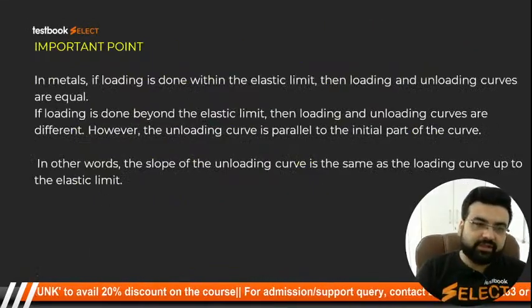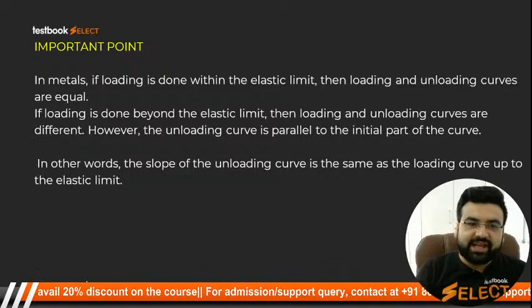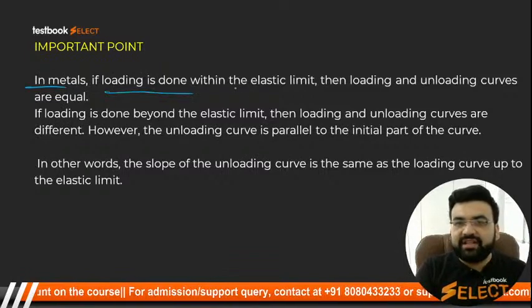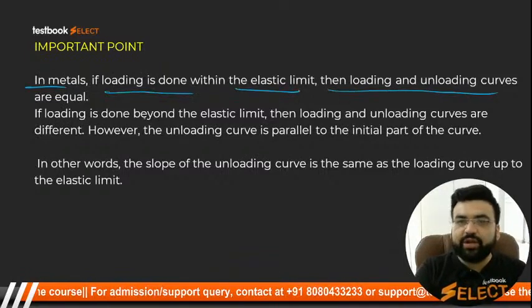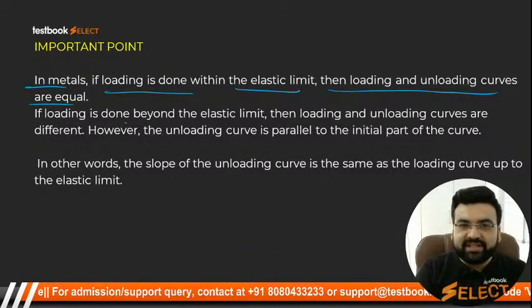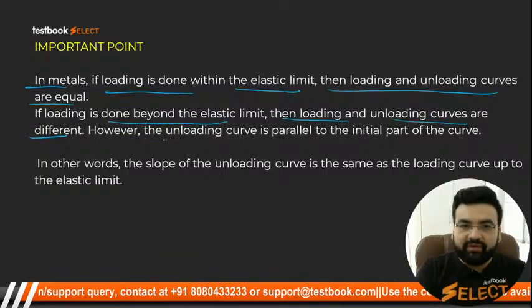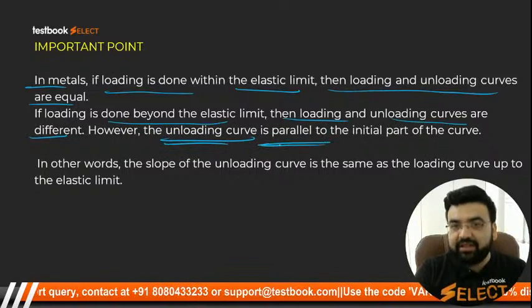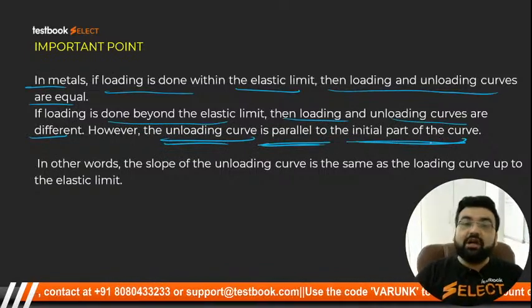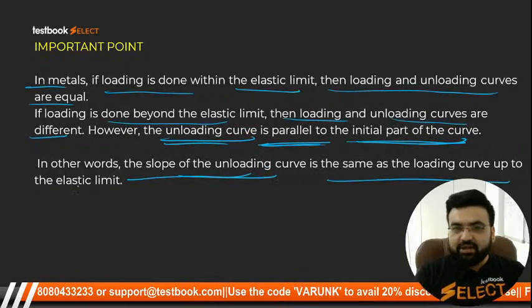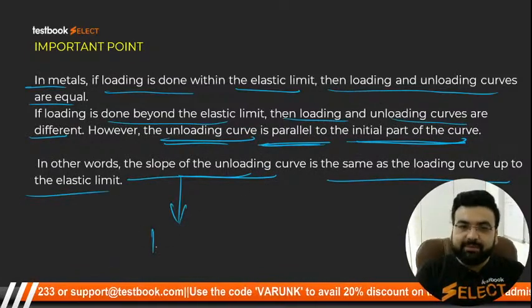Now, this is important. I have already told you this. In metals, if loading is done within the elastic limit, then the unloading and loading curves are equal. If loading is done beyond the elastic limit, then the loading and unloading curves are different. However, the unloading curve is parallel to the initial part of the curve. In other words, the slope of the unloading curve is the same as that of the loading curve. This is a very important concept, students.